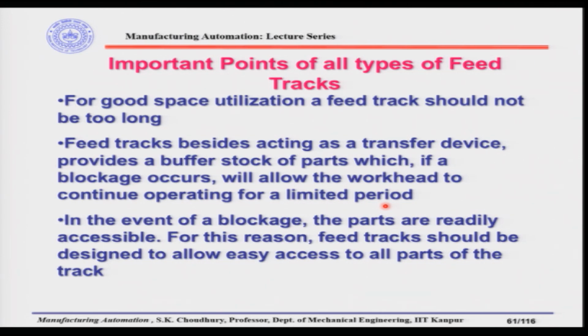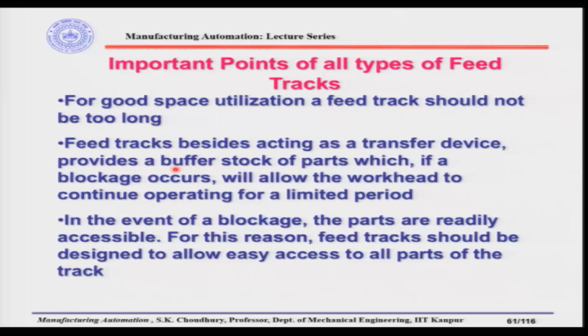Initially we said that it should not be too long, but it should be sufficiently long so that parts can be stacked as a buffer stock. Suppose the bowl feeder stops, the assembly machine can still get the parts which are stacked inside the feed track. So, the feed track can work as a buffer stock, for a certain time, of course.